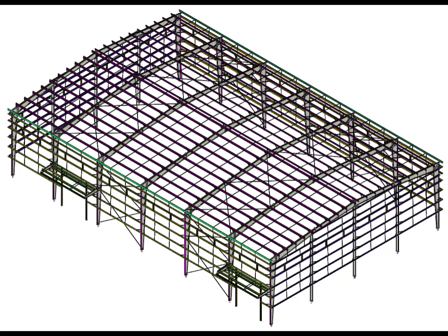Now that we know what a Girt is, the next question is more important. Where do we actually find it? A wall Girt is normally located horizontally between the vertical structural members of the wall framing system. If you look at a typical PEB wall, the main columns are the vertical primary members. Between these columns, horizontal members are arranged at different levels. These horizontal members are the wall Girts.